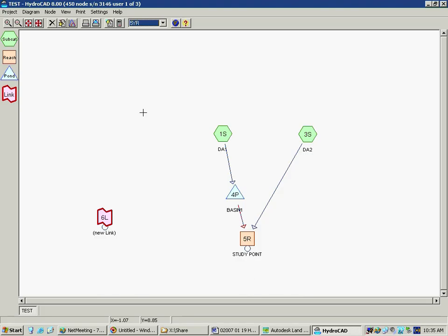They should let you use TR20. TR20 is actually SCS. TR55 is a tabular method generated from TR20 because you have to do it all by hand. So that's why computer programs always use TR20, because it's the original method and calculation intensity doesn't really matter.